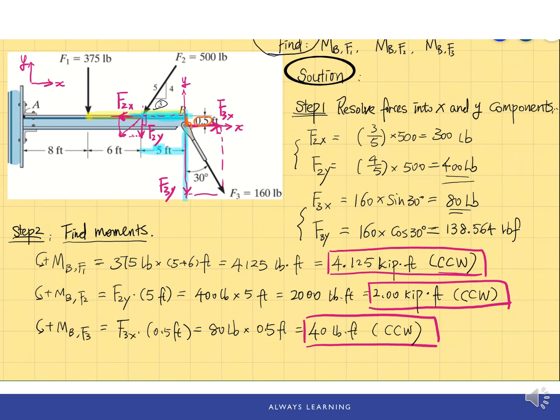Then if the force passes through a point, or if the point is on the line of action, then the moment of this force will be 0, which will simplify the solution of this problem. And then we find the moment of the components that do have moment about this point, and we need to determine the rotational direction, clockwise or counterclockwise, and decide whether we need to add the components together or subtract one from another.